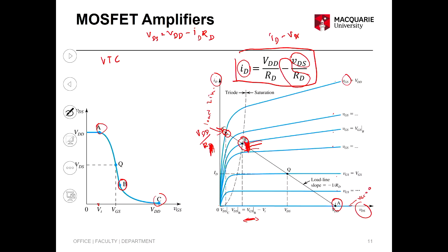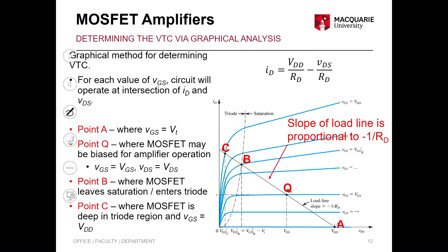Now, for LNAs, most likely you will be biasing somewhere in here. That means you probably bias at a lower VGS, like 0.5 or 0.6, because if you increase VGS again it could become noisier, and you have a noise figure to meet. I'm not sure whether it will get noisier, it might. And you might also find it's hard to match sometimes, so slight changes matter. So this is the summary of what I've told before.